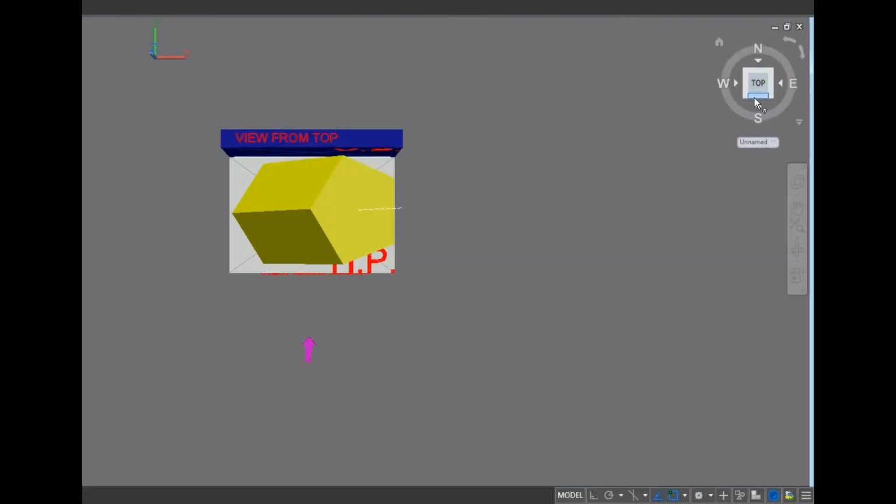And in the top view you will find that there will be a pentagon which is visible in the top and two rectangles, but the bottom rectangle has to be covered also with hidden lines, because the edges are there but not visible from the top. That is why we will draw those longer edges in hidden lines. Also, before drawing these views we first have to assume that it is directly standing on the HP, and we will draw a pentagon and rectangles. Then we will tilt the views obtained from that assumption. Now we will see how to draw this.